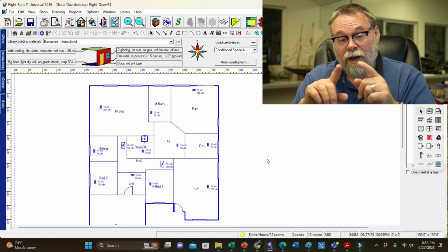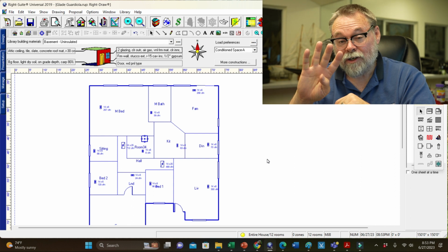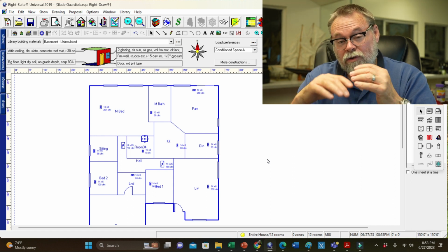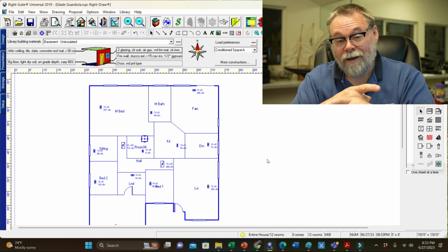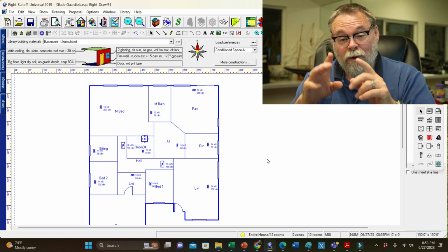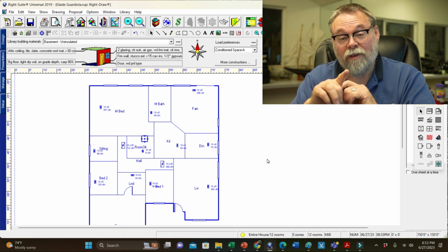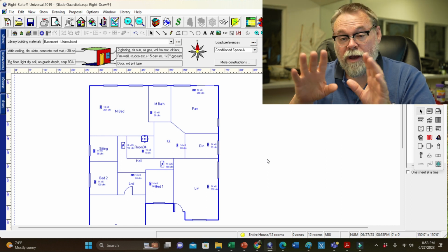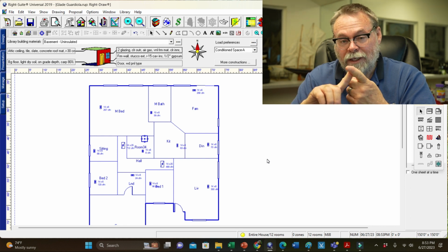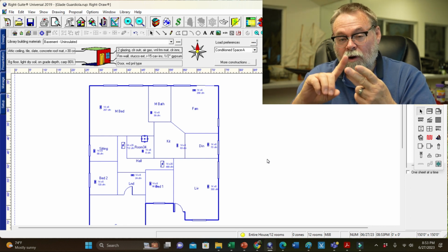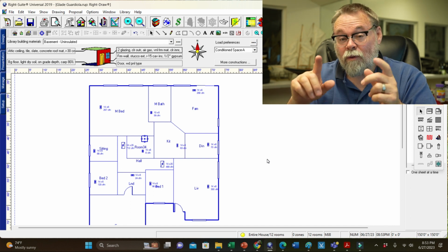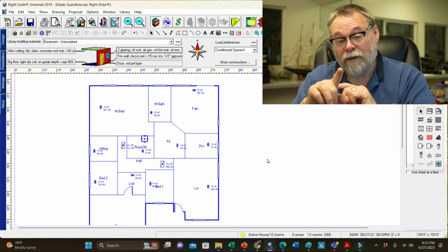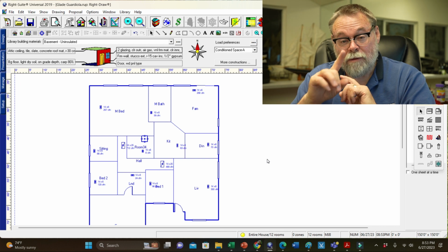This is why you do load calcs, because this lady has a 4-ton air conditioner currently, and we usually went a half-ton bigger whenever we did the load calcs, and I'll show you exactly why you should do a load calc, because the way her house is built, she could get by with a 3-ton or 3.5-ton, no problem. Plus, it'll be less expensive to run. It will cost less to buy because it's a smaller piece of equipment. So she saves money all around if she switches to a 3 or a 3.5-ton. We're going to talk to her afterwards, but let me show you why.